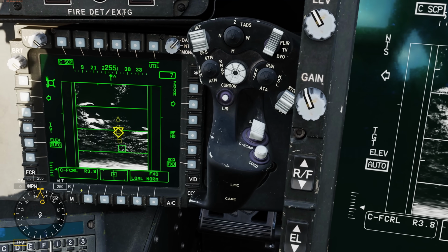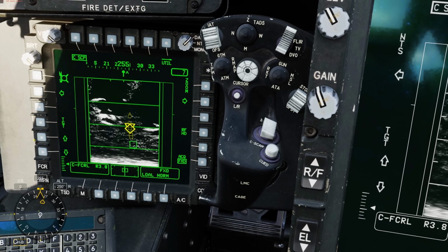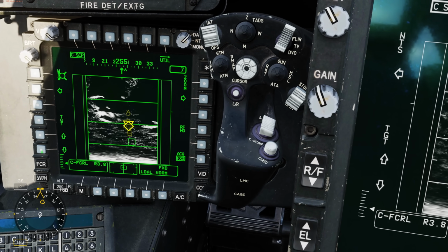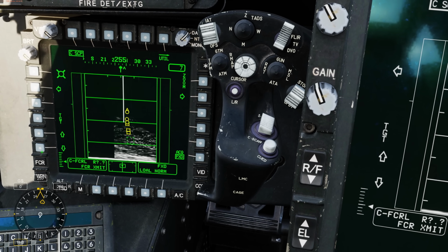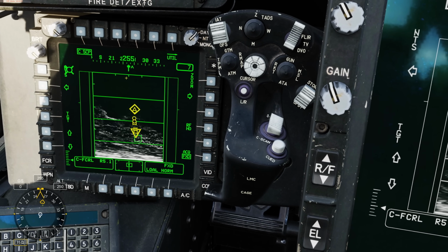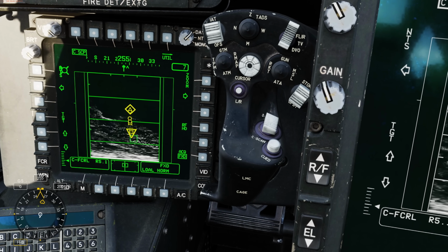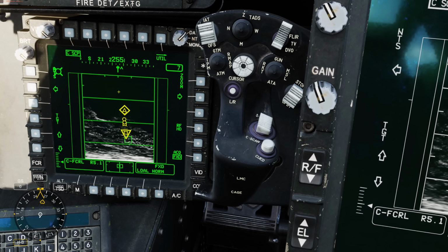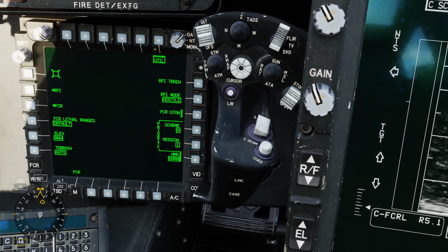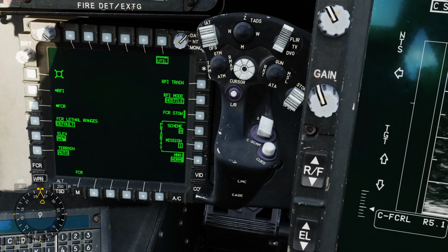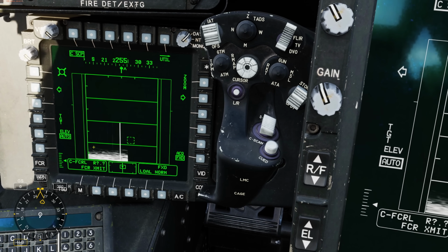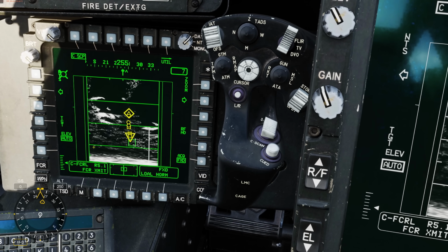So in this case, let's go to the display, elevation, to manual. Let's say go down one notch, rescan. You can see now I'm looking too low, and at the top it's black, indicating that I'm looking too far down and I'm missing terrain at a little higher elevation. But I want to go back to automatic. Again, utility, elevation controls in manual, back to auto, back to the page, rescan, and we're good to go.